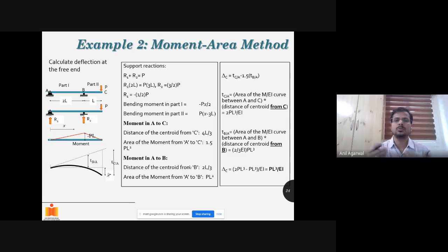curvature to slope and slope to deflection. And curvature itself exists only for flexural members. That's why double integration method is applicable only to beams, or frames which are primarily deflecting in flexure. Fine. So it cannot even be used for frames which are actually compressible.